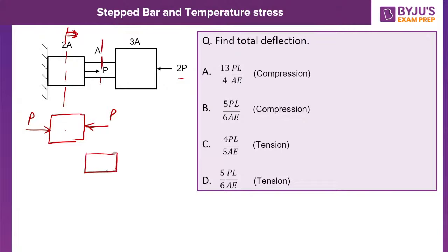If you stand at the center, you will find that a 2P is acting here and 2P is compressive in nature. So that's all. 2P is acting towards this side, and once you get the 2P from this side, you don't have to worry. From the other side also you apply 2P force in the opposite direction, because the block must be under static equilibrium.